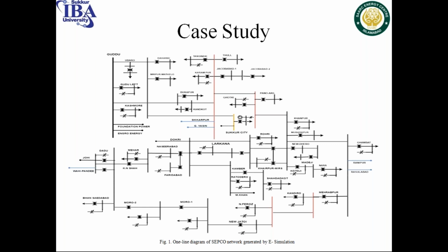So with the shift of the angle, this angle correction will be done, which happened due to the flowing of negative sequence voltage and zero sequence voltage, and the current contribution, which was the power loss contribution, which was due to the negative sequence and zero sequence currents. It can be compensated with the reactive power supplement of the capacitor banks. Actually, they supply the reactive power. So this reactive power will be helpful in compensating those losses.